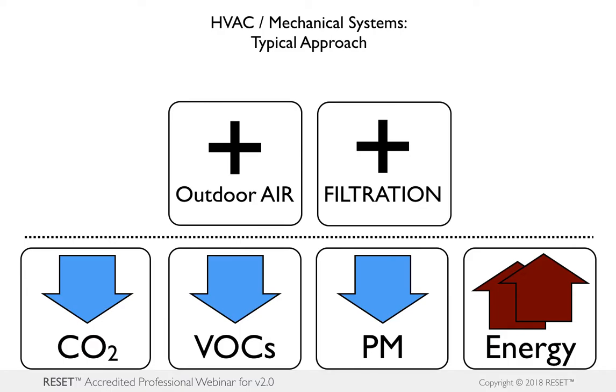So the second line of defense is to just add more filtration, or any filtration on top of your outdoor air that you're bringing in. And this strategy requires a lot of extra energy. It takes so much more effort to force that air through the perforations, the tiny spaces in the filter media, and that added resistance equals added energy that you need.